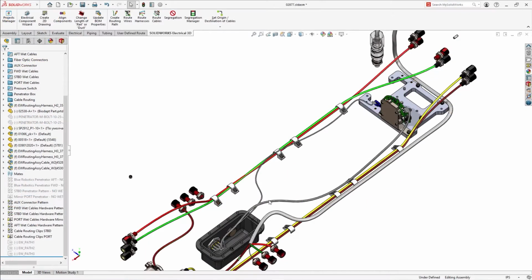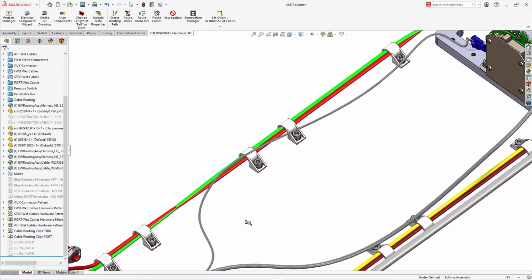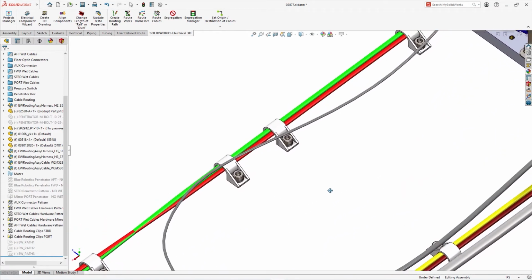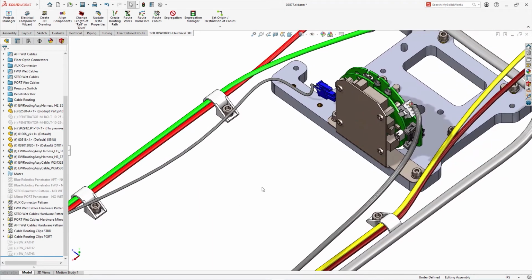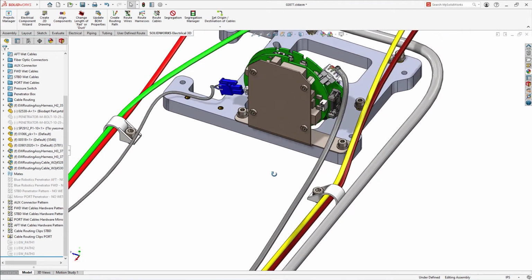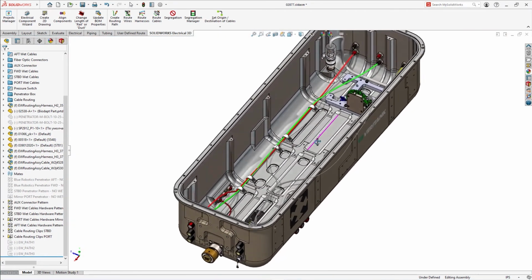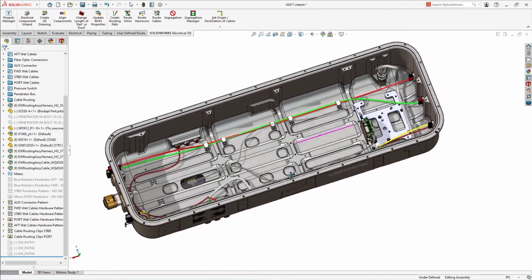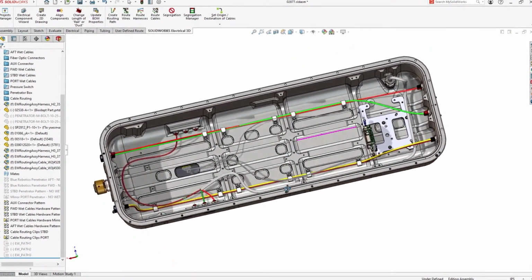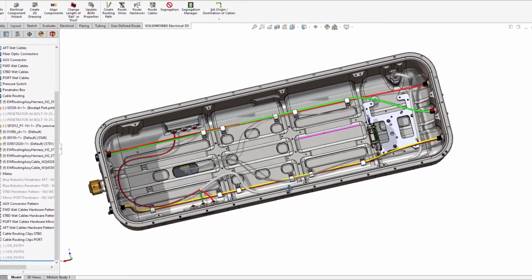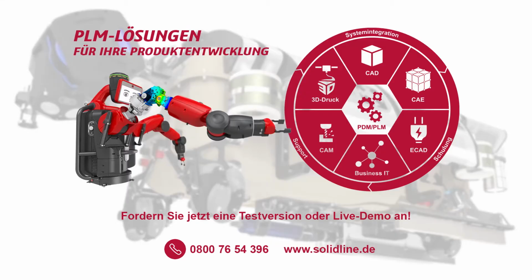We already created 2 separate routing paths, one for each cable starting from the round 10-pin connector that brings signals from the outside world and connects to the PC board that controls navigation sensors. We will choose to route these 2 cables at once and as separate assemblies. This new separate routing of cable assemblies allows designers to create more complex and more feature-rich functionality by bridging the needs of mechanical, electrical, and electronics disciplines.